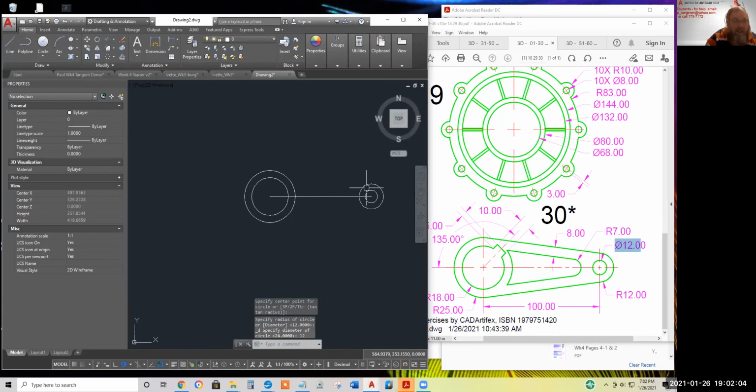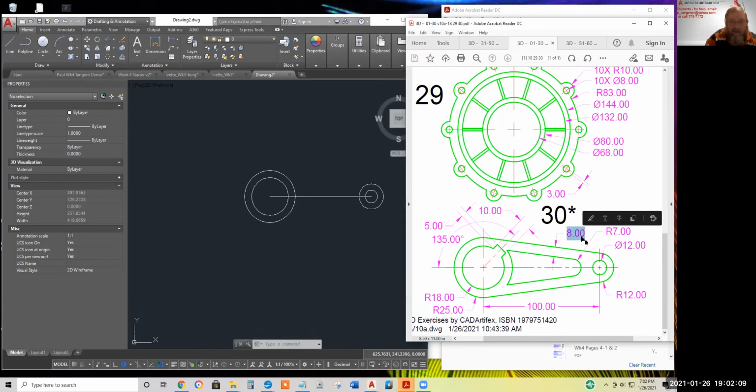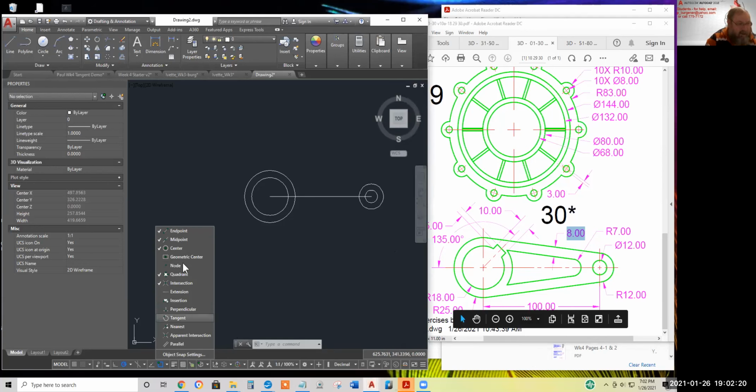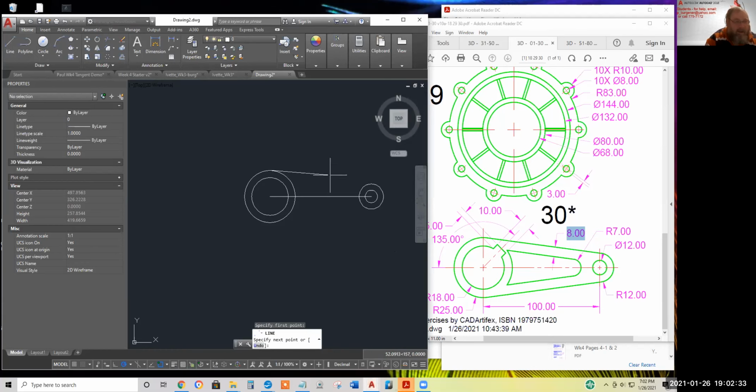And I need tangent to tangents. Then I'll offset the tangent to tangents. And then I'll trim and fillet. Easier done than said. We'll go back to, looks like tangent to tangent. No need for endpoint, though I don't believe it'll hurt. Just tangent. Line. Tangent to tangent. I could mirror this across, but rather than look for the mirroring icon, I'll proceed.